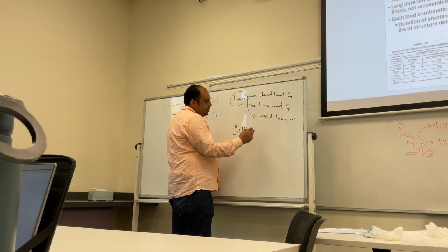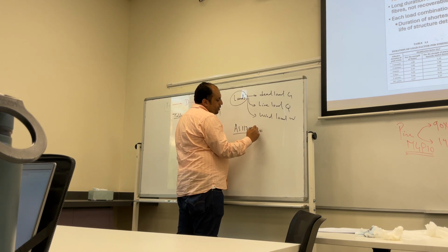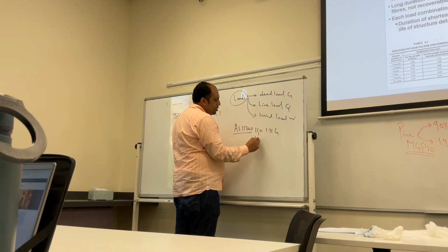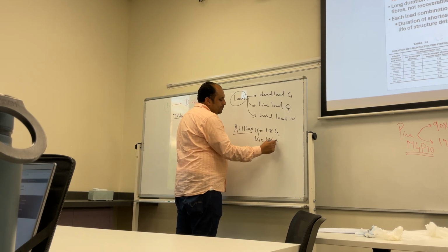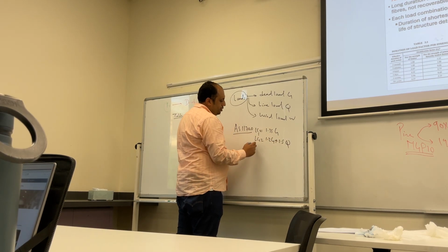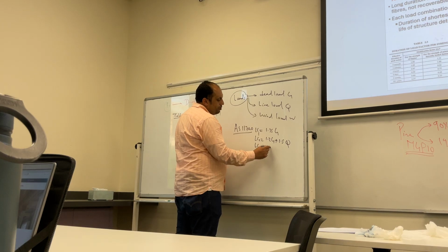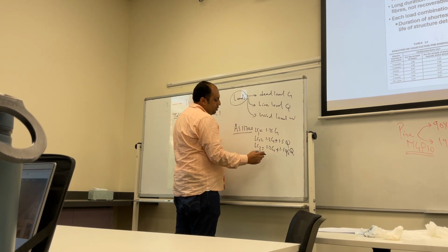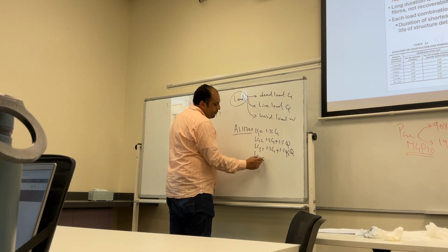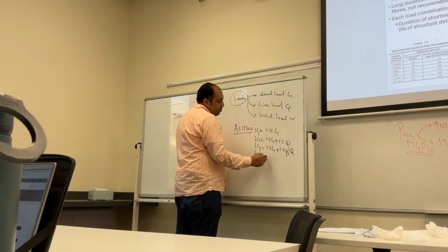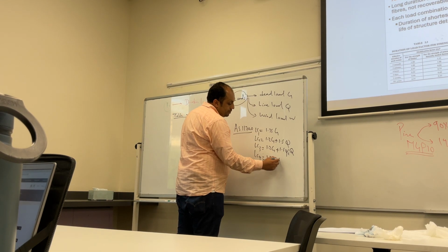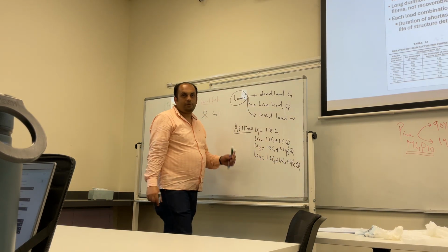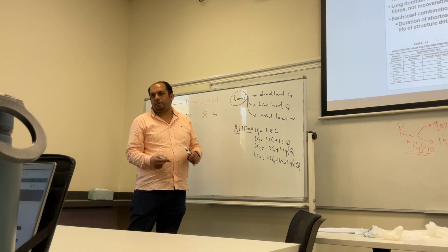Load combination 1, 1.35G, load combination 2, 1.2G plus 1.5Q. 3, we have 1.2G plus 1.5 psi CQ. Number 4, do you remember, 1.2G plus W plus psi CQ, and so on. So I have loads and load combinations.